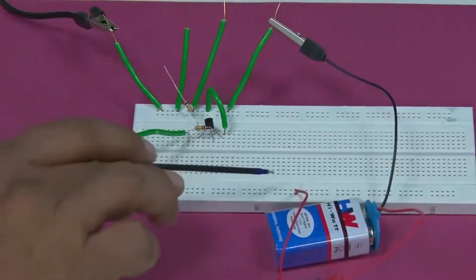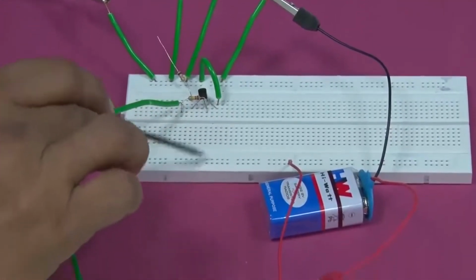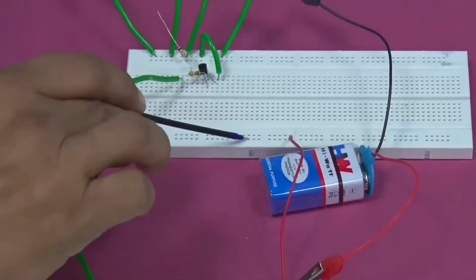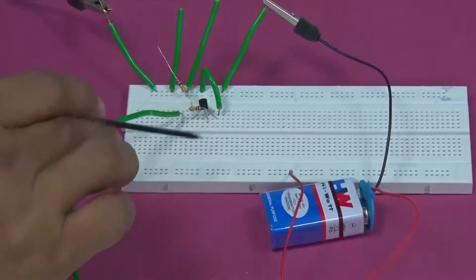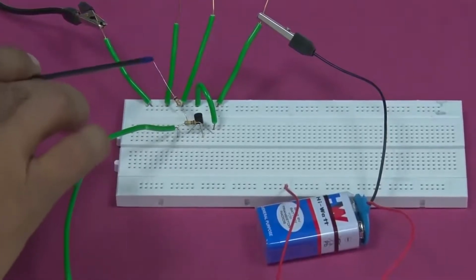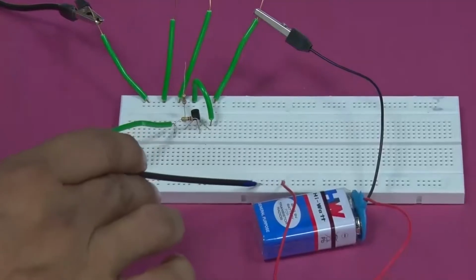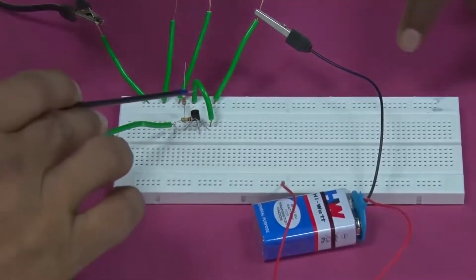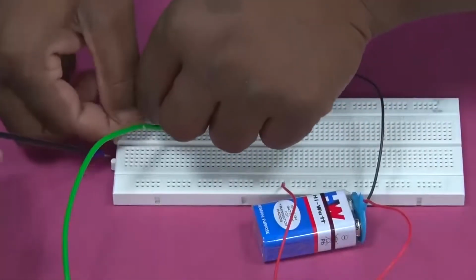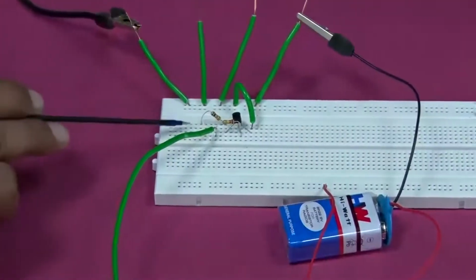Good. So, this is our 9 volt line. This whole line here becomes 9 volt. Okay, all these holes are at 9 volts. Fine. So, the collector has to be connected to the resistance that you have added, and the other part of the resistance should get connected to this line somewhere. You can join it anywhere you like, you can join it here. And then from here,